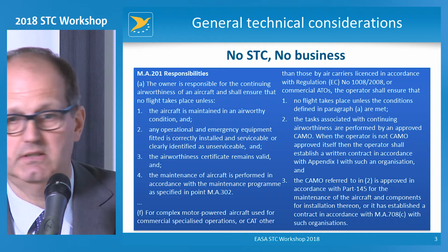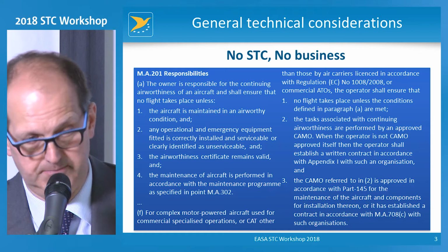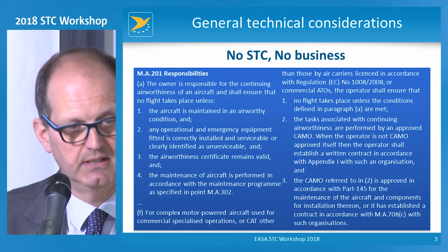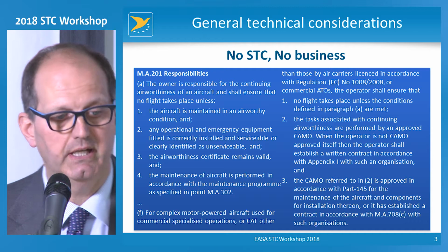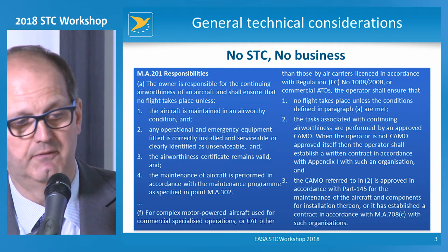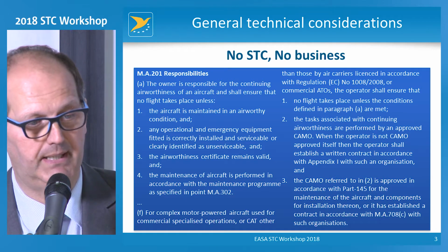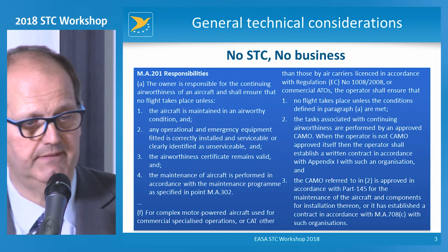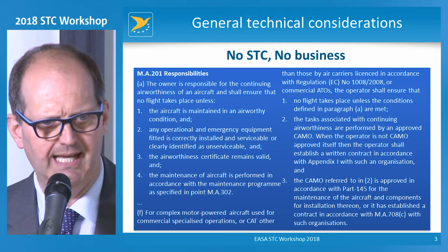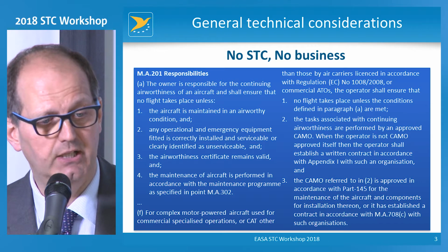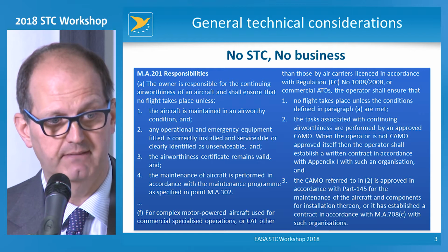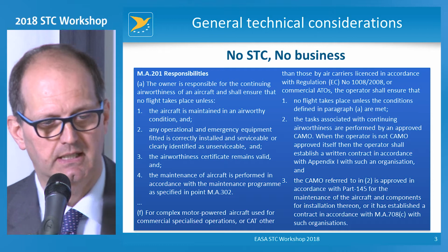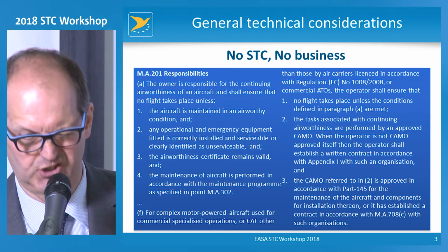And this is not because we are saying this, but this is in the rule in Part M. When the responsibilities of the owner for continuing airworthiness are spelled out, first point in the Part M, you read A1, aircraft is maintained in an airworthy condition, and any operational and emergency equipment fit is correctly installed and serviceable and clearly identified or clearly identified as unserviceable.